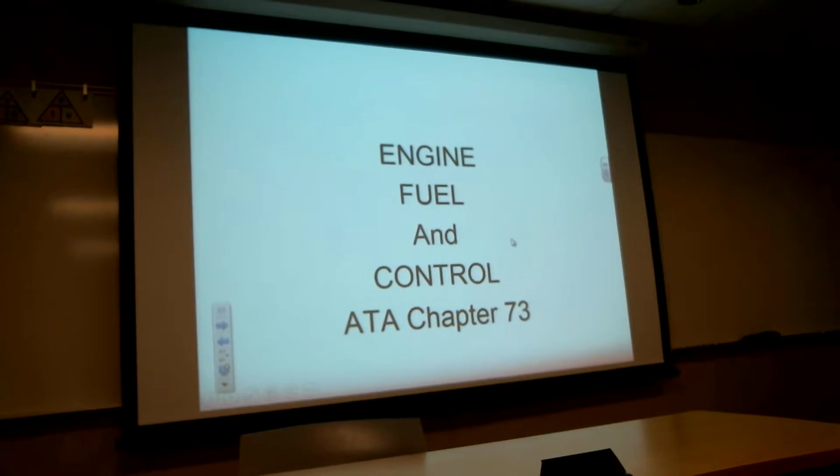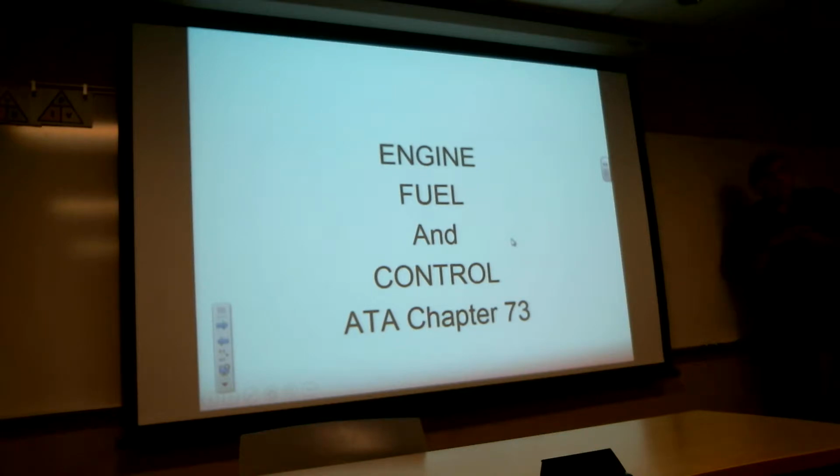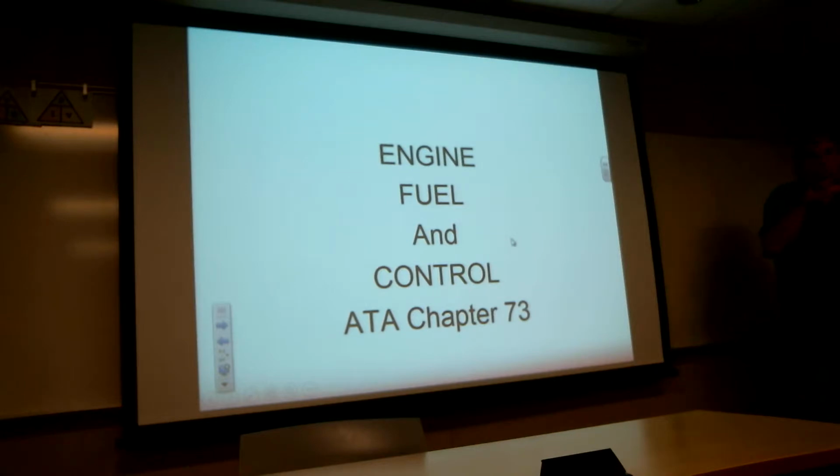You would remember it. So let's say you needed a gasket or an O-ring for a fuel nozzle when you install it. That's where you find it, right there. If you go look at the parts catalog, it's going to be under 73. Now, a lot of times these parts manuals may not show you a picture of maybe an O-ring, but it'll tell you about the assembly. So it'll tell you that you have a gasket, an O-ring, a nozzle, and it'll list all the individual parts, but you may not necessarily have a photograph or a line drawing of that part.